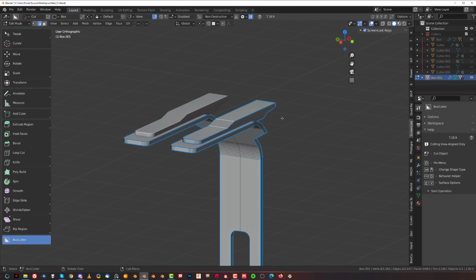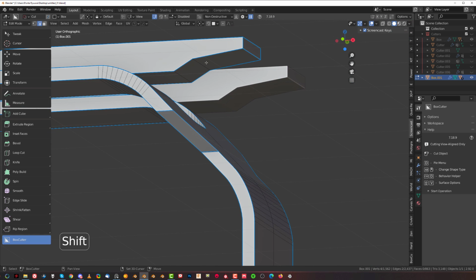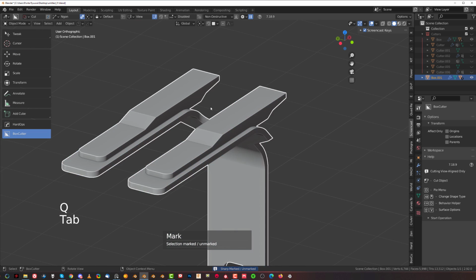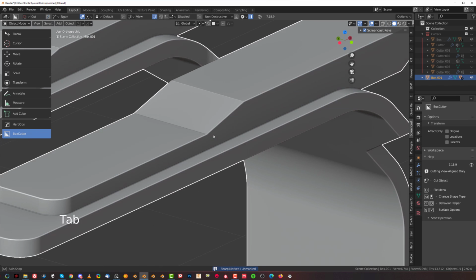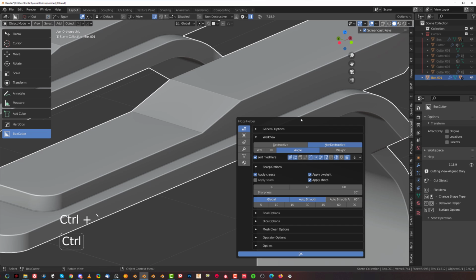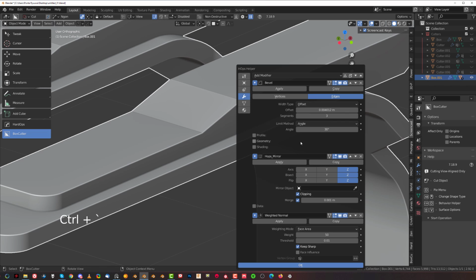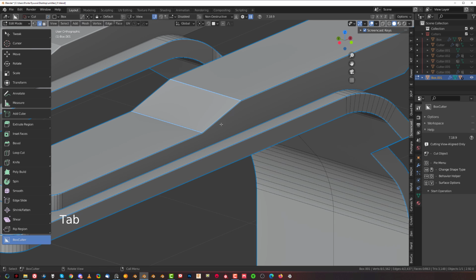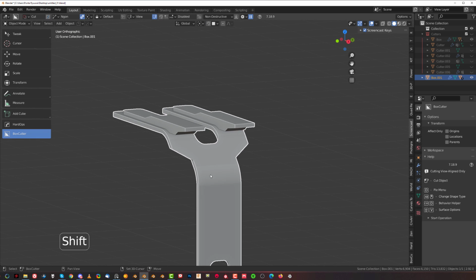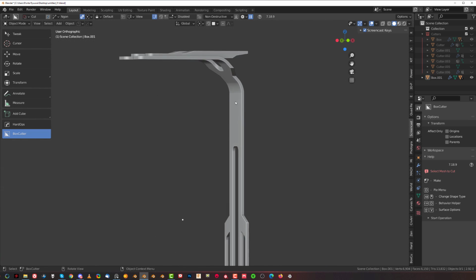And we're gonna simply apply them here manually because we will need to switch the way the bevel runs. So let me explain why, okay? See, bevel doesn't catch in here because the angle is too shallow. So you can now either change the auto smooth angle, or you could just simply switch here to weight because we are running weight on these edges, and now you can see there's a bevel in here. So there you go. Awesome. So we got that going on.